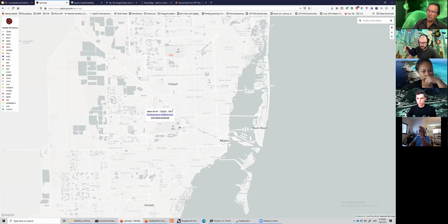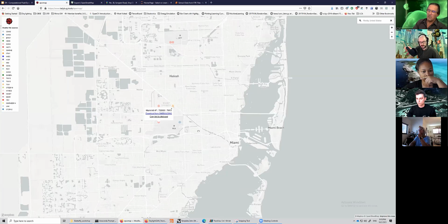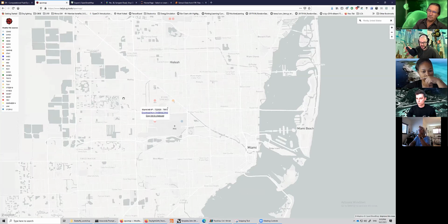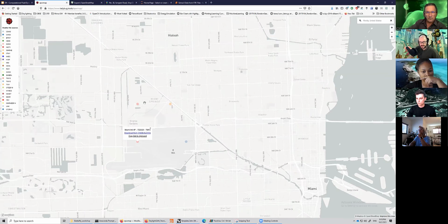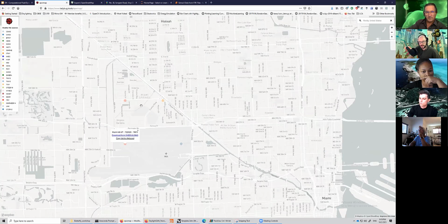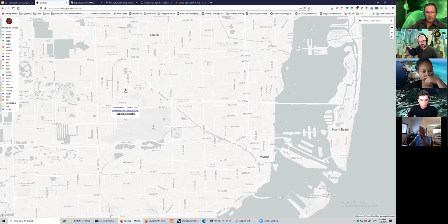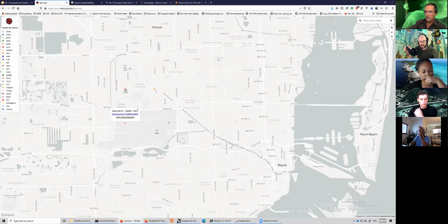And I chose the airport file. Usually in cities, and this is quite interesting, you can find weather files in the cities. These are interesting, but they are not always good for this sort of studies because you can imagine the measurements are already sort of polluted by the buildings, right? So we go to the airport usually because there is an open area. It's a sort of not very turbulent flow, right? This is why we try to calculate that.